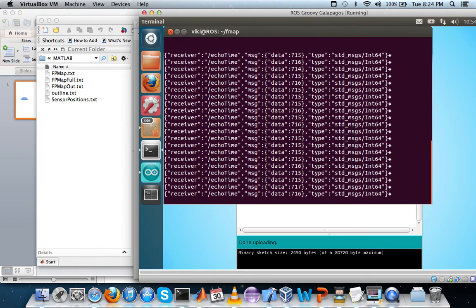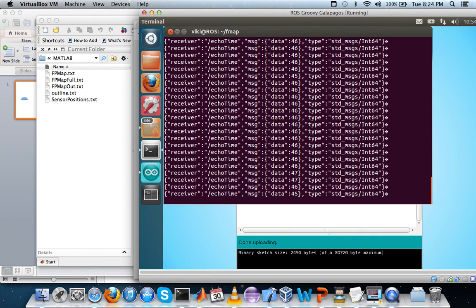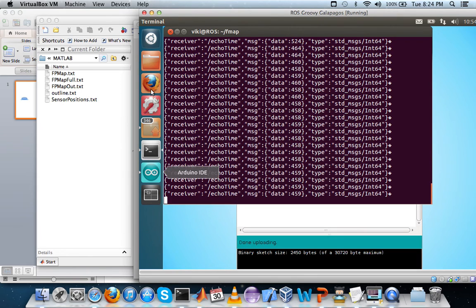And then with a SOCAT command, you can get the input of the pot pin displayed on the screen. As you can see now, the input is around 700. And if I turn the pot pin, it goes right down to about 46, 45. And then I can turn the pot pin back up, and it goes back to nearly 700 again. Of course, using these values, you can then pipe the input from the Arduino through Netcat, and then write a HTML5 and JavaScript document to display the pressure map on the screen in real time as the input is coming in from the Arduino.